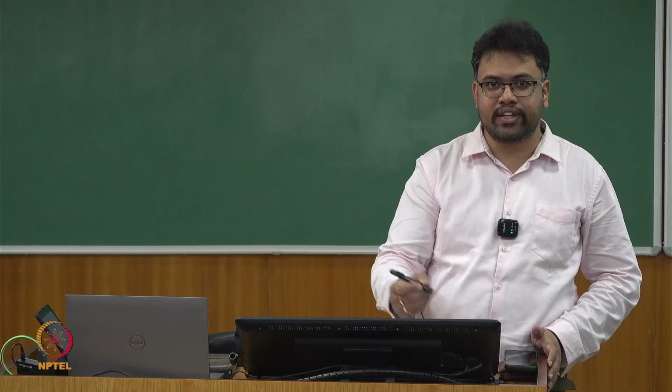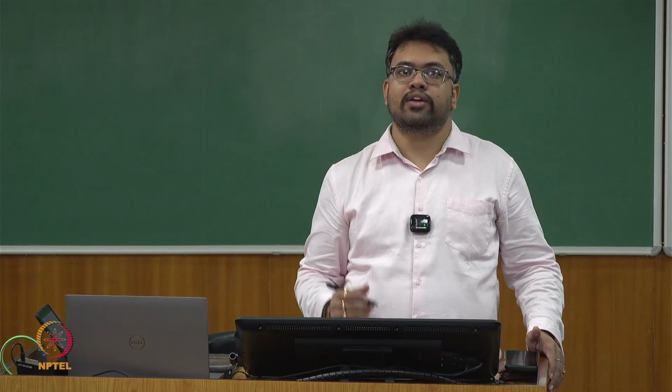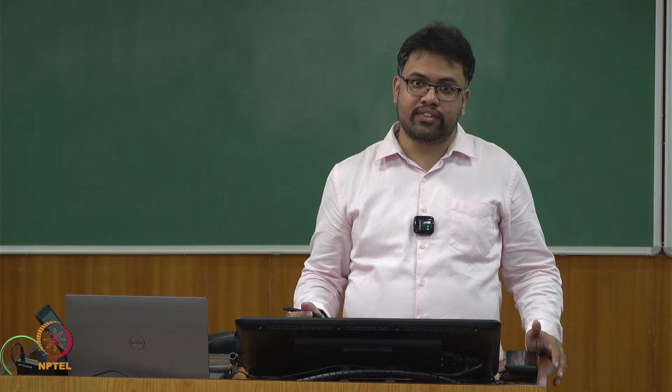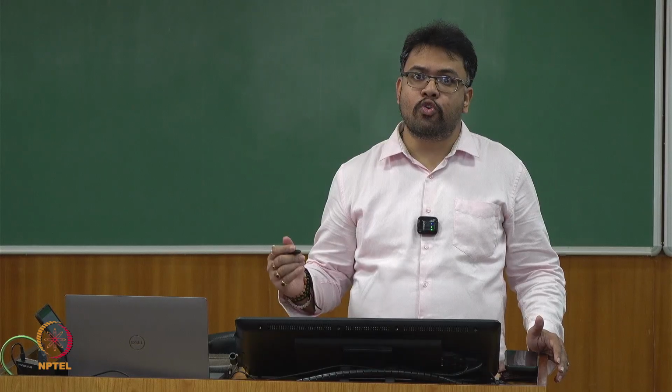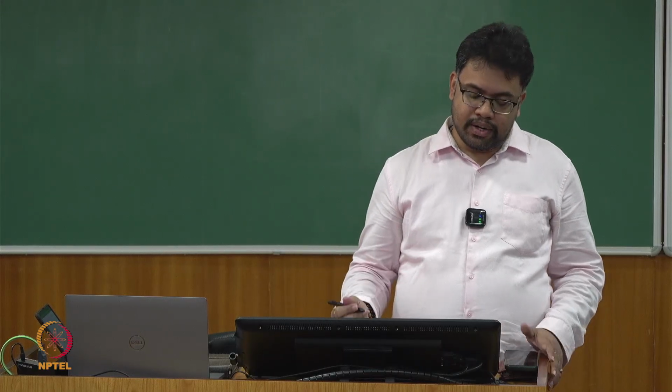If we have some general type of function, we can write our equation of motion m x double dot plus c x dot plus k x equal to force. So this equation is a second order non-homogeneous ordinary differential equation.